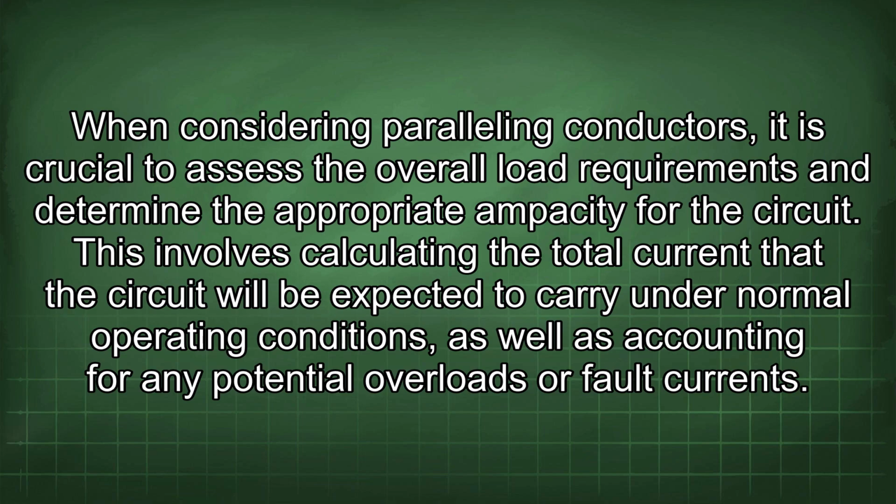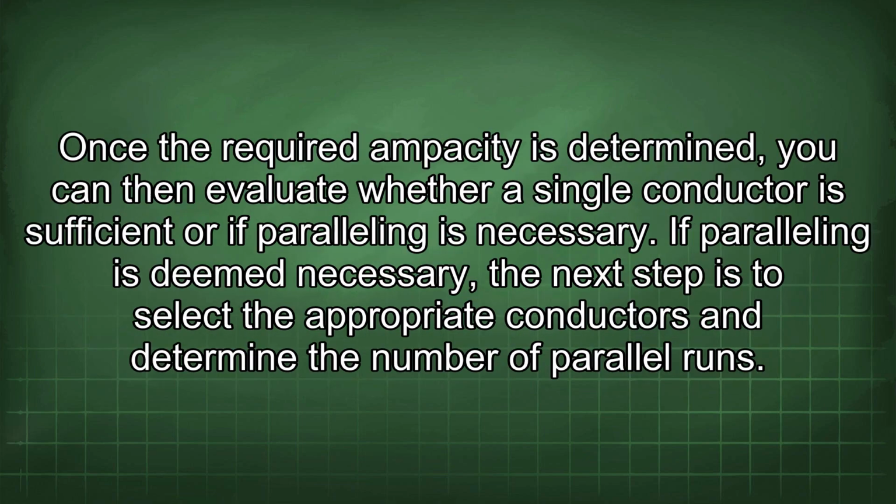This involves calculating the total current that the circuit will be expected to carry under normal operating conditions, as well as accounting for any potential overloads or fault currents. Once the required ampacity is determined, you can then evaluate whether a single conductor is sufficient or if paralleling is necessary.